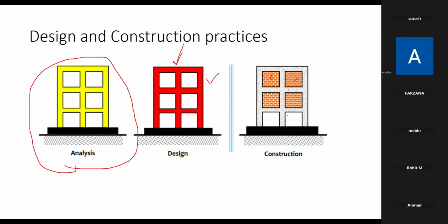In most of the buildings we have infill walls in the ground story also. So here I took a particular case where there is a possibility that in the ground story they will not use an infill wall, which means this space they use for some function. For example, mostly in a densely populated area, they use this for car parking. So they just use it for car parking, which is highly functional and considered more important in this kind of building.